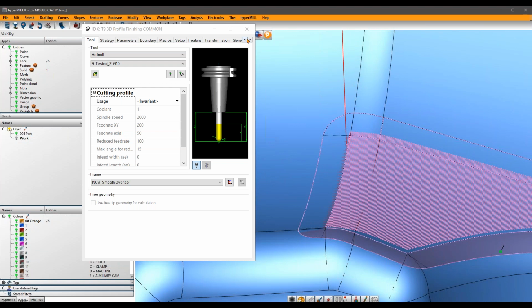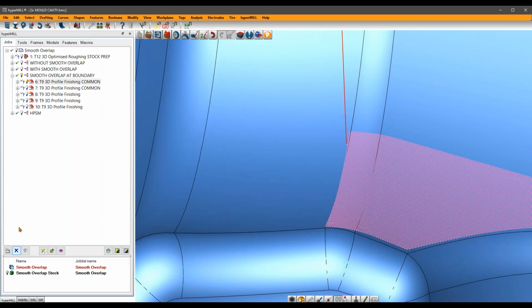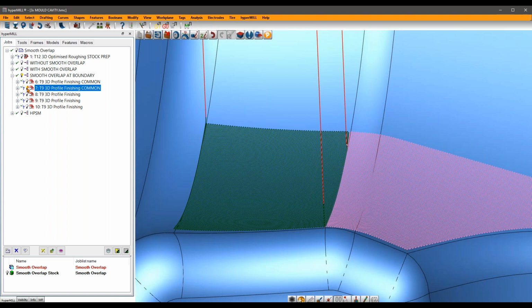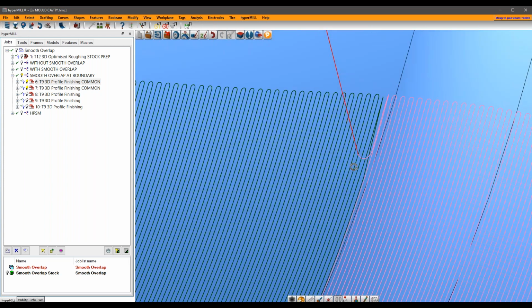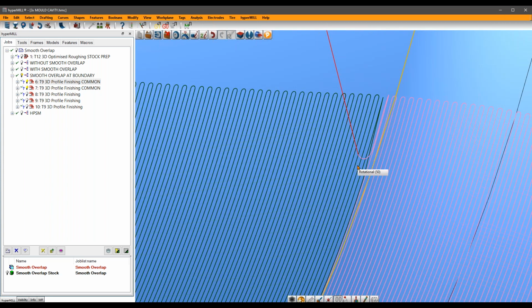And I can see I've got a nice clean scanning toolpath, one on the other side. What we get is a join line in the middle. So in this instance, because it's the same toolpath being used, the smooth overlap function doesn't work here, okay? Because we're not requiring slope mode. Slope mode is when you're wanting to blend between the steep and flat areas. This can be used for the same toolpath, flat area to flat area.